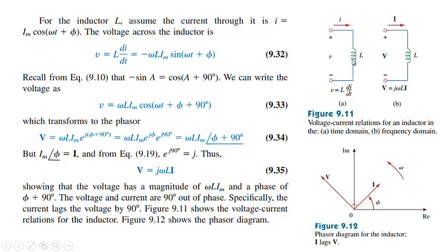but you need to be very careful here. This voltage and current are the voltage and current of the inductor itself, that is, the voltage appearing across the inductor and the current flowing through the inductor. That is which relation we are talking about. That means the voltage across the inductor leads the current flowing through the inductor by 90 degrees, or conversely we can say that the current flowing through the inductor lags its voltage appearing across it by 90 degrees. This is also very important.